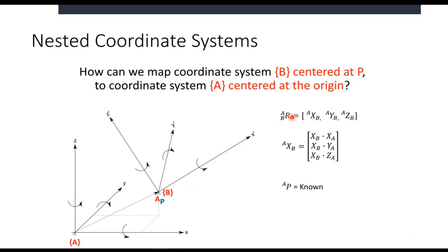So this notation is a rotation matrix from coordinate frame B, the one that we're going from, on the bottom, into coordinate frame A, the one that we're going to, on the top. And just like we talked about our points having this pre-superscript, that'll be consistent. So you can look at the top left to figure out where we're ending up. If I want to take this coordinate frame B and express it in coordinate frame A, I just have to project them. So let's do just the x-axis for now.